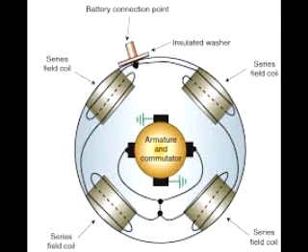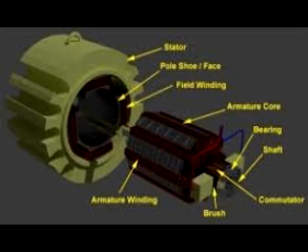As total current increases, motor speed will increase, thus motor torque will decrease. However, once you put a load on the motor, the rotor current will increase, causing the rotor field to increase. If the rotor current increases, then the shunt current will decrease, causing the stator field to decrease. This will cause the motor speed to decrease, thus the motor torque will increase. Shunt wound brush DC motors have the performance characteristic of decreasing torque at high speeds and a high but more consistent torque at low speeds.